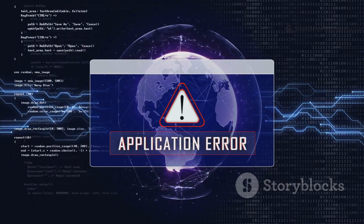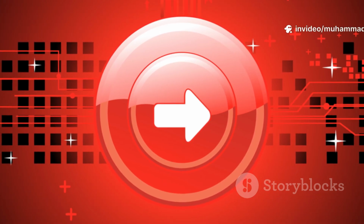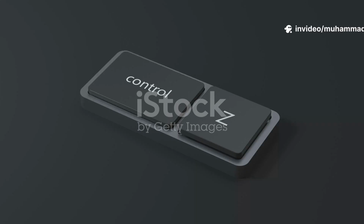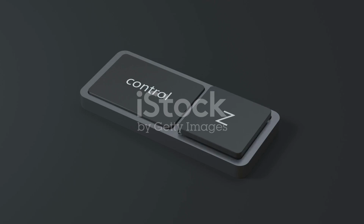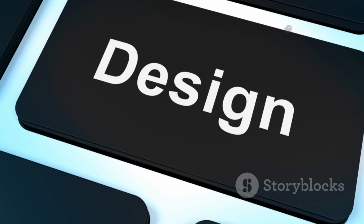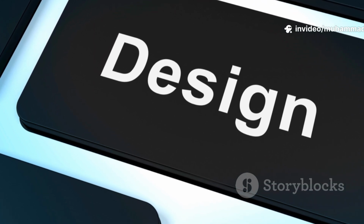Mistakes happen. Here's how to fix them. If you can't select a shape, make sure the selection tool, black arrow, is active. If shapes snap or move oddly, check the View menu and turn off Snap to Grid or Snap to Point. Made a mistake? Use Undo, Ctrl+Z on Windows or CMD+Z on Mac. Lost your artwork? Go to View, Fit Artboard in Window, or press Ctrl+0, CMD+0 on Mac.